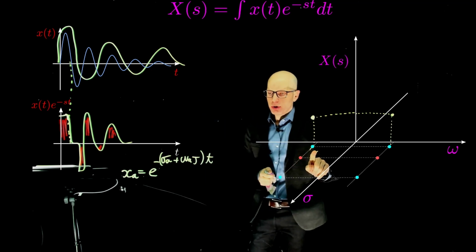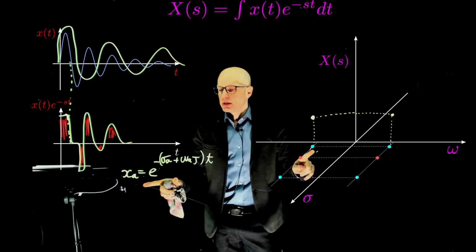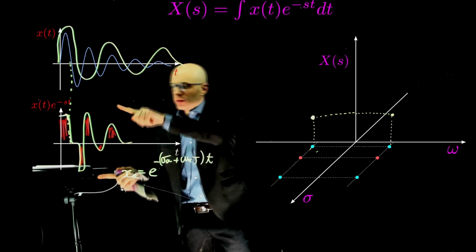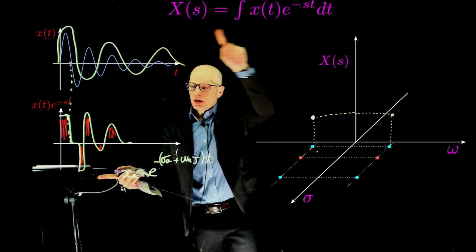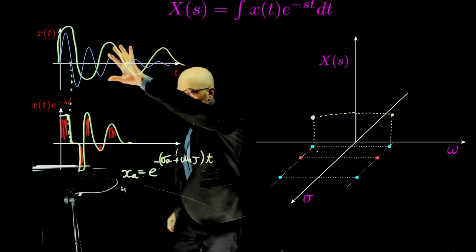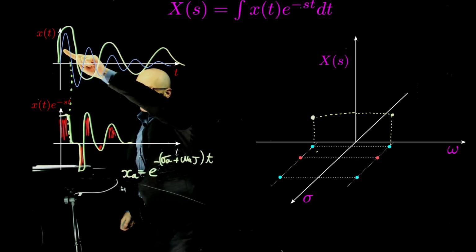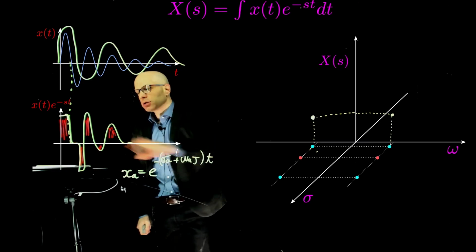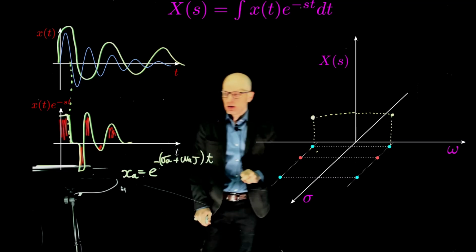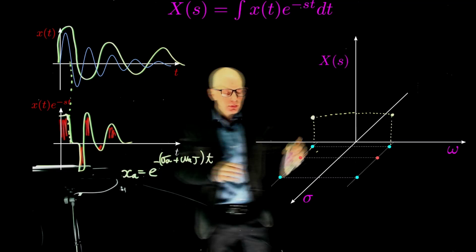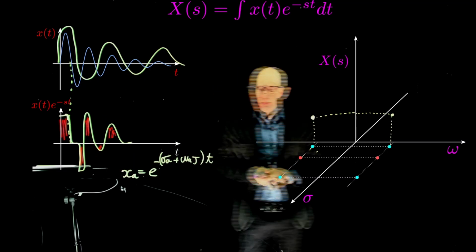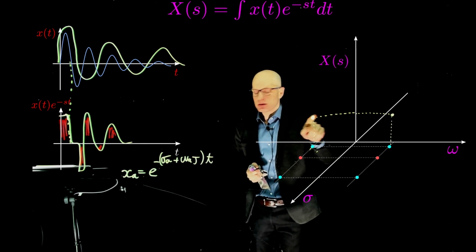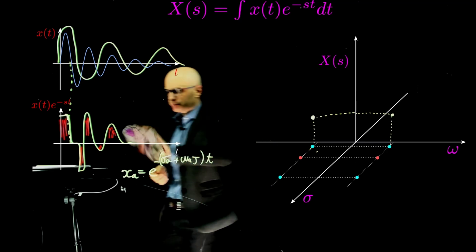So we picked a random point here and created a random signal. We multiplied the signal with our original signal. Here is the multiplication. We took the integral, and because these signals don't match, we see portions of the multiplication that are positive and portions that are negative. So when you take the integral, we are taking the net area here. Because they never match, there are positive and negative components. The result of the integration is a finite number, and this is the result of that.